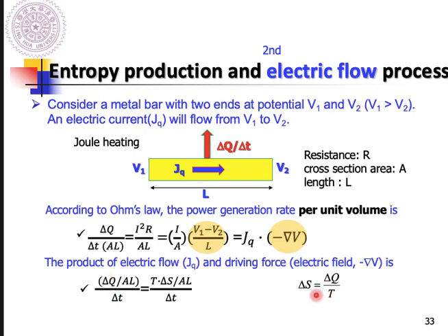You can write down T delta S, right? So now you got the entropy term, right? Okay. So what's this term? Actually, it's the entropy production rate per volume. So this term can equal the absolute temperature times the entropy production rate. And both these are the same, so this equals this.